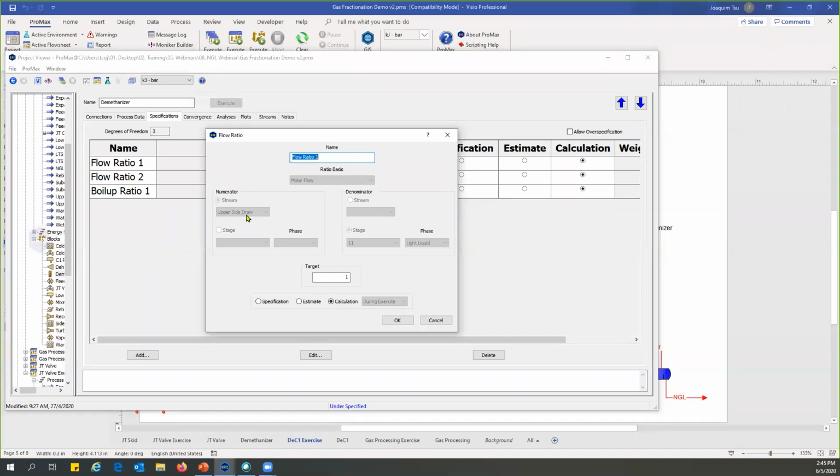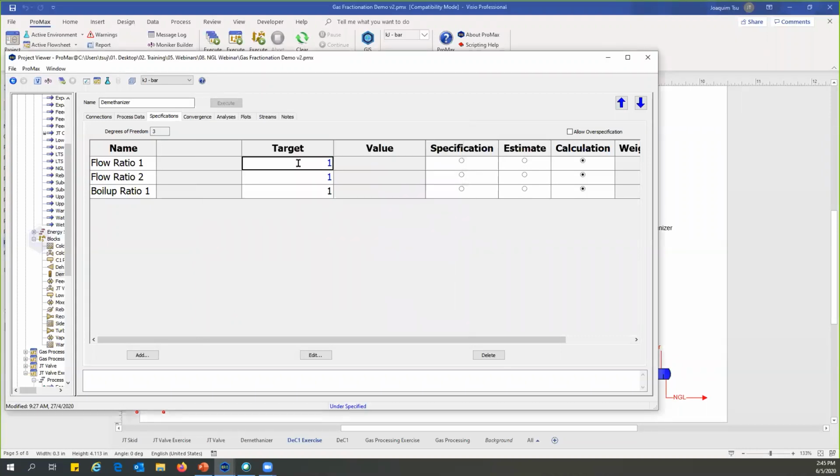And it's just a ratio of how much liquid goes below the tray and how much liquid is sucked out of the tray. If I put a very high value, for example, 50, it means for every 1 kg that goes past the tray, 50 kg will be drawn out. And this will be very specific, and this will allow us to basically approximate a full draw. Of course, there are more precise ways of doing this. This is just a quick approximation for the purposes of this webinar.